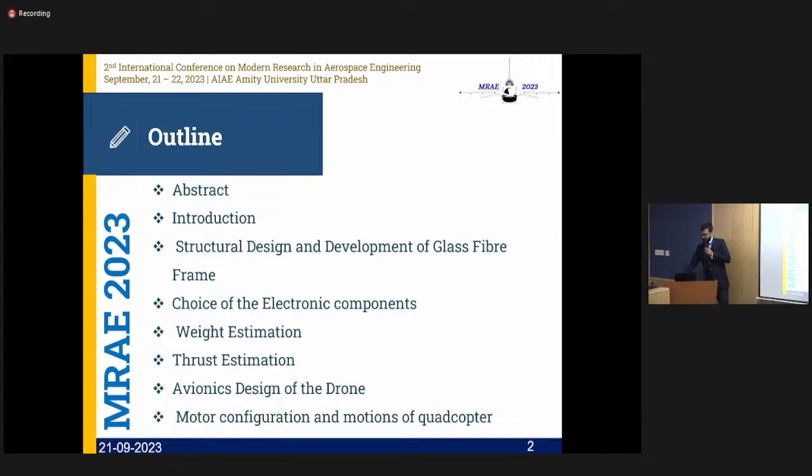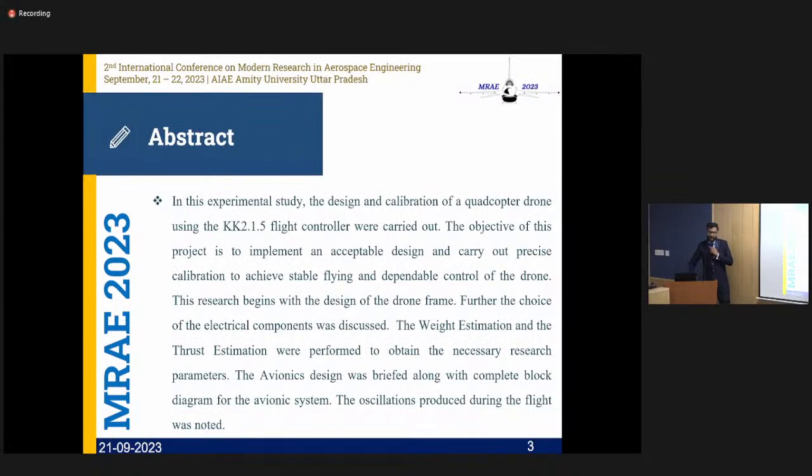You may be wondering why I say weight estimation every time. Every time I am using a different payload, a different material, for a different purpose, and with different motors and propeller combinations. That is why I need to consider weight estimation as a very serious method in order to obtain the exact weight, which in aeronautical terms we call the all-up mass, or the takeoff weight.